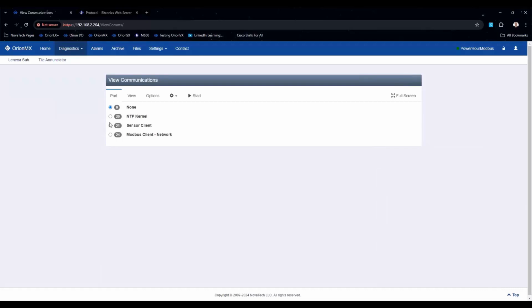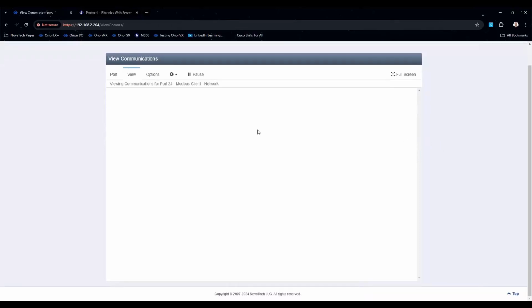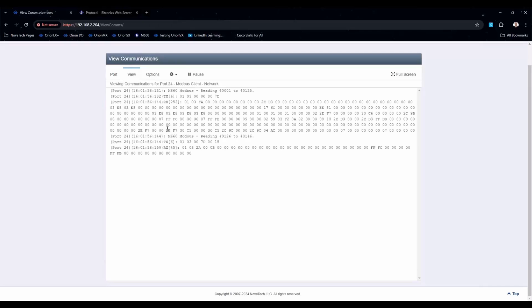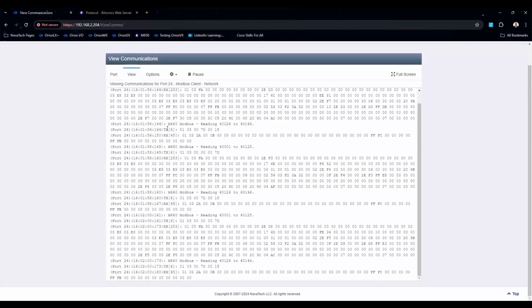Now that is a troubleshooting tip, kind of an accidental one, but certainly something to look at. Make sure any Modbus protocol instance you configure is fully configured with points and everything.